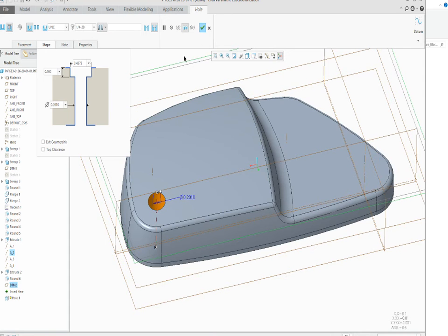So once I've done this, we've got the profile, everything's in to go, and then here we can also look at how much it's giving me. Is it giving me a clearance hole? No, it's just giving me the size of the thread, so that's not good. So we want to do a clearance hole, and we want it to be free fit. So 266 is excellent for a 1/4.